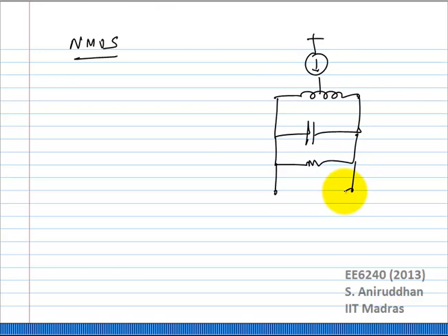That is very easily done, right? A center tap inductor will occupy not much more area, but now there is a difference. The inductance of the center tap is 2L. Right? What is the capacitance? The way I have drawn it, it has to be C by 2, and this resistance has to be 2R. Correct?